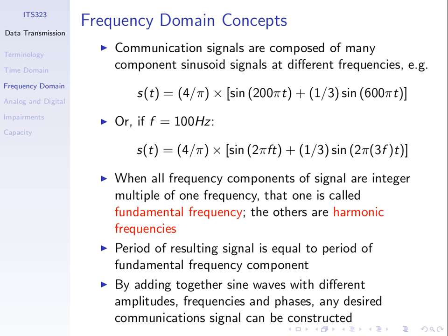We saw yesterday that for the basic sinusoid, a sine wave, there are three parameters that impact the shape of that sine wave: the peak amplitude, which is a multiplier which increases the amplitude; the frequency, which changes how often a cycle is repeated over time; and the phase, which visually we can look at as a shift of that sine wave relative to some origin point.